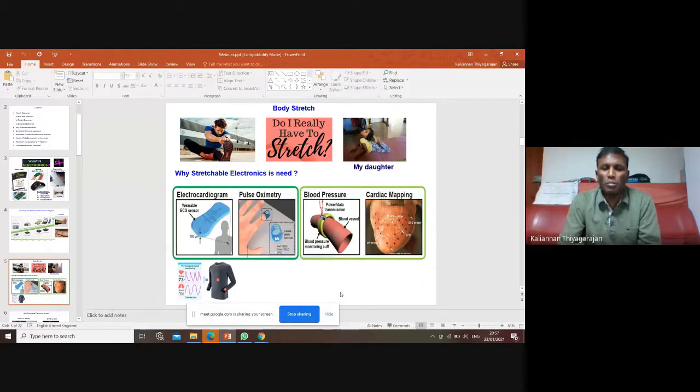If you start from a bottom-up approach, you will get material, but the conductivity will be problematic, as well as the quantity. But if you want nanosheets, then the modified Hummers method will be good. In thin film form, CVD is now industrialized, and they are growing graphene on copper foil, so a very large film is possible.